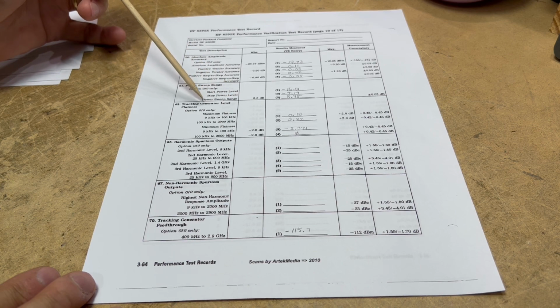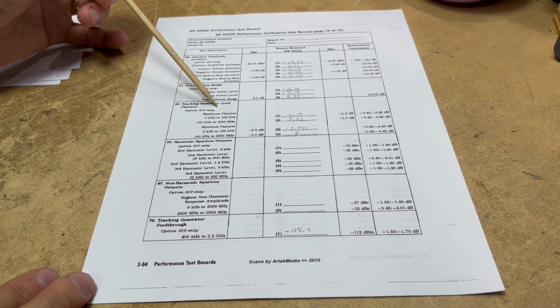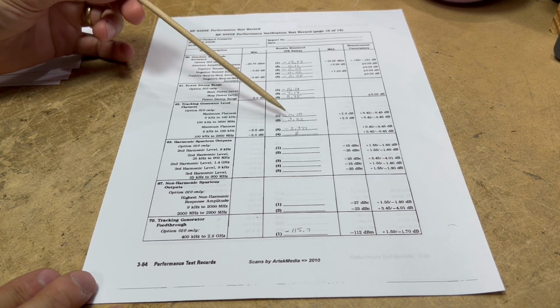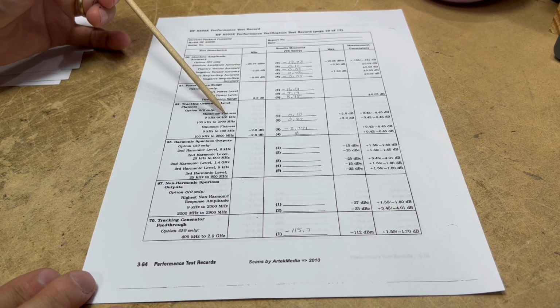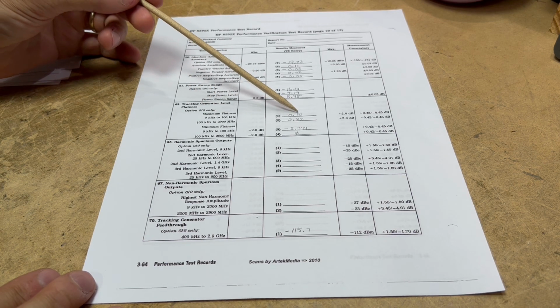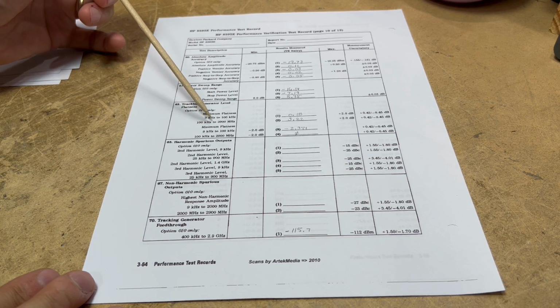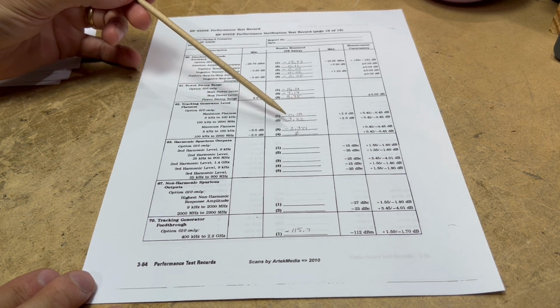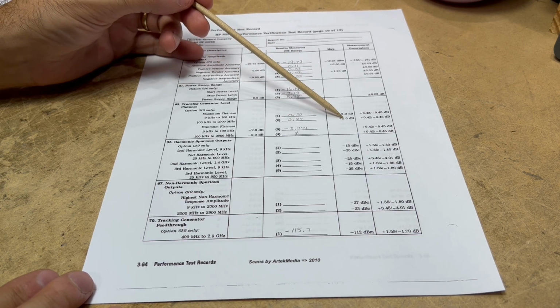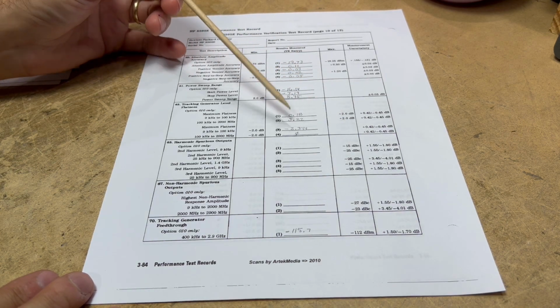Now the level flatness, which is what I expected, I was not going to meet, and it didn't come anywhere close. So from 9 kilohertz to 100 kilohertz, that was fine, 0.18. For 100 kilohertz to 2.9 gigahertz, the maximum deviation measured was 3.82 dB, where the spec is 2 dB, so well over the limit there.